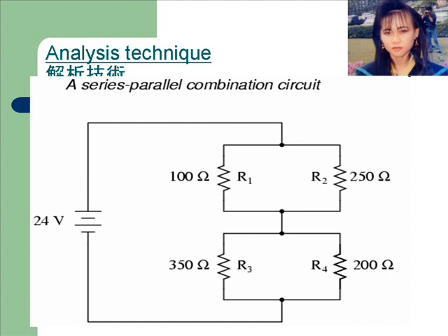If using a table to manage variables, make a new table column for each resistance equivalent. Step 3: Repeat steps 1 and 2 until the entire circuit is reduced to one equivalent resistor. Step 4: Calculate total current from total voltage and total resistance, I = V/R.